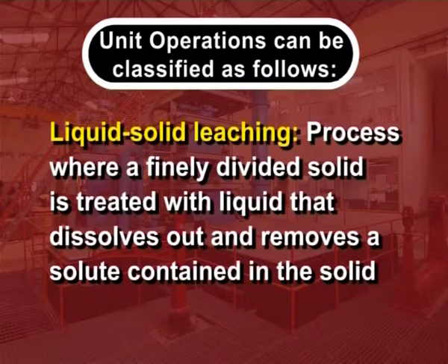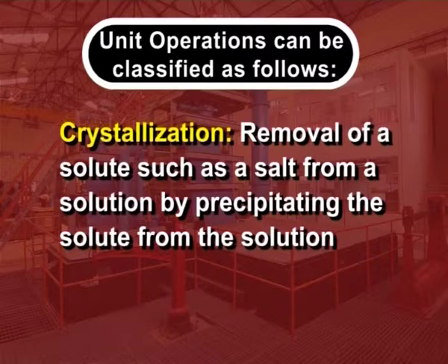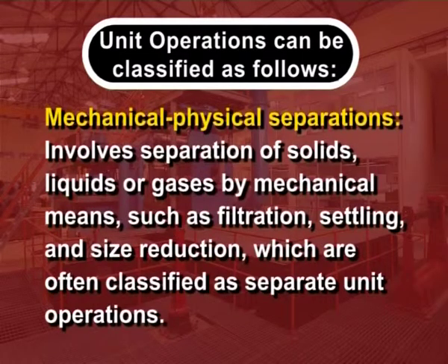Liquid solid leaching, a process where a finely divided solid is treated with liquid that dissolves out and removes a solute contained in the solid. Crystallization, removal of a solute such as salt from a solution by precipitating the solute from the solution. Mechanical physical separations, this involves separation of solids, liquids or gases by mechanical means such as filtration, settling, size reduction, which are often classified as separate unit operations.